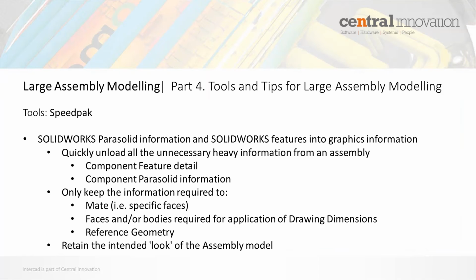Moving on to the next slide. What is SpeedPAK exactly? If you're not familiar with SpeedPAKs, basically the SolidWorks Parasolid information and SolidWorks features are converted into graphics information. It quickly unloads all the unnecessary heavy information from the assembly, including the component feature detail and the component Parasolid information.